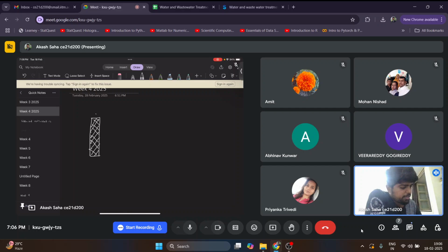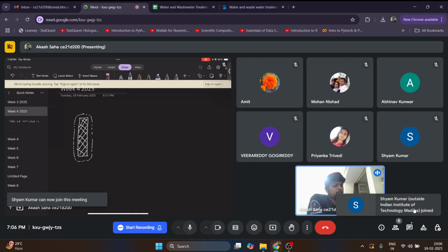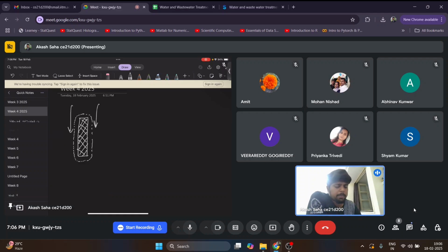Okay. So over it, there will be a kind of biofilm forming. As the wastewater flows through it, it comes in contact with this biofilm and the degradation will happen. Whereas in any other tank, a suspended growth tank, the microorganisms are free to move throughout. So there are chances that they will come out from the outlet.